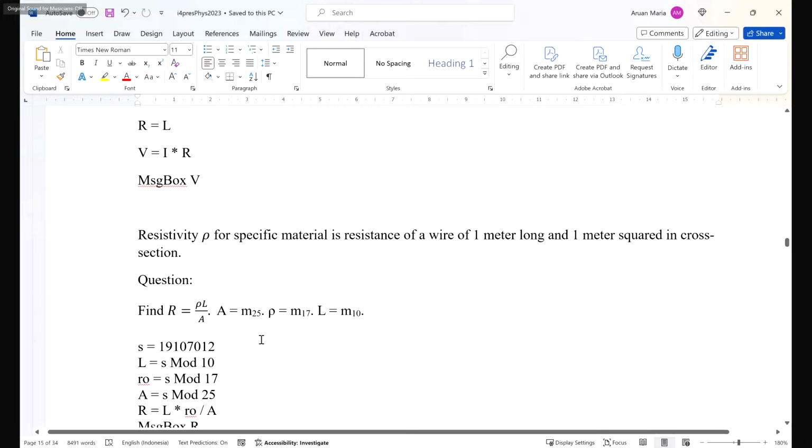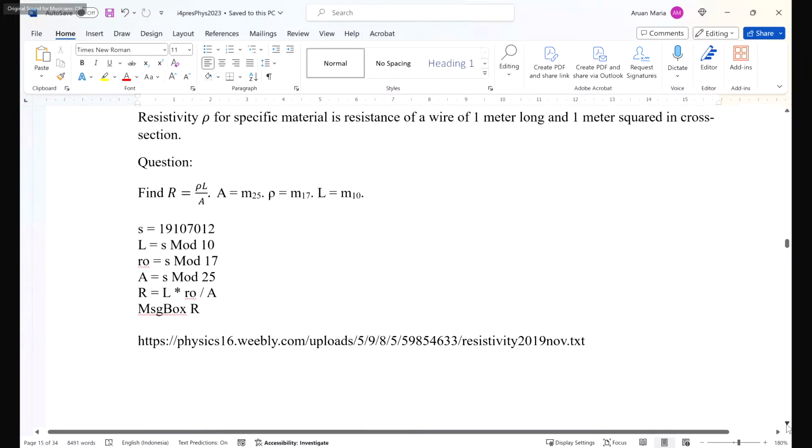It is very important because depending on the resistivity, we consider the material either a conductor or semiconductor or something which does not conduct electricity at all, isolator, okay? It will be very, very important for later on, but now let us calculate resistance given the resistivity, okay? Just length times the resistivity divided by cross-sectional area. Questions, please. Comments, please.